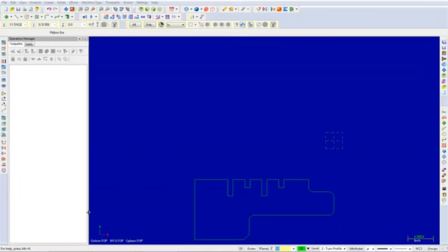In this video, I will cover the setup sheet, tool settings, and stock setup for tutorial number 9. The setup sheet shows 7 tools that will be used to cut the part. The first tool is a general turning tool, face, with an 80-degree angle. This tool will be used to face and rough the part.